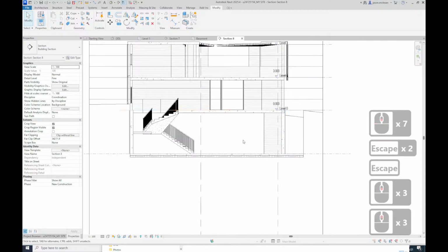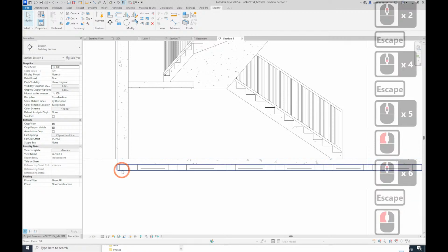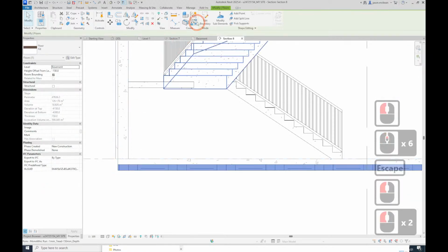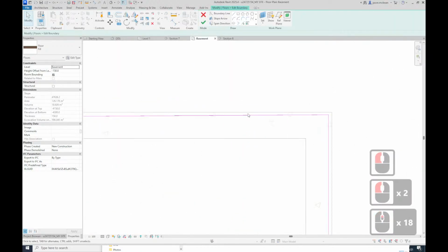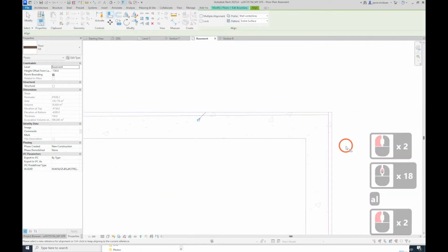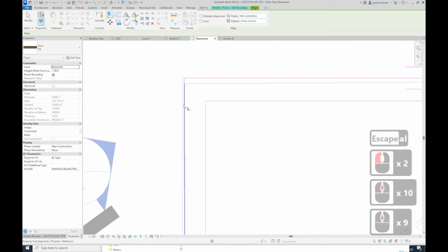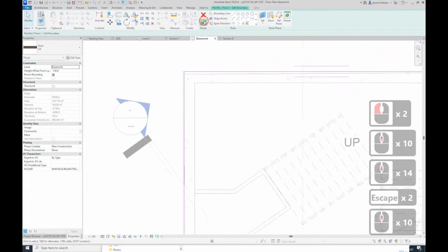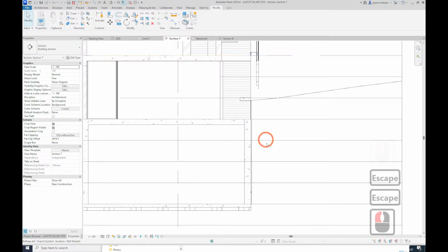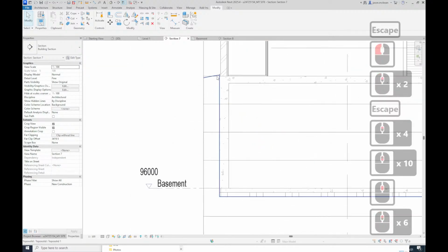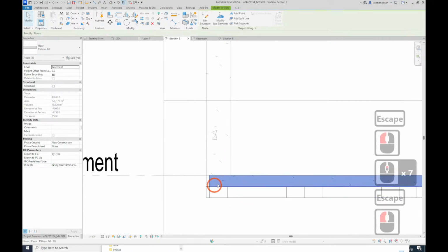Okay, so what I'm seeing is cool. This is perfect. So how exactly do you get that gap? Oh, you see here. If I want to fix this now, I just go edit, boundary, basement. I just go align, watch this, it'll fix it now. Bang. Watch this, align. Now it's cutting properly, now it's excavating properly. See now, maybe to that line of the wall, the floor slab's gone a bit whack. But now, if I go to my section, you'll see that it'll start cutting this correctly. And I'm using this to drive it and not my floor slab. Now your floor slab's a bit whack, you see.